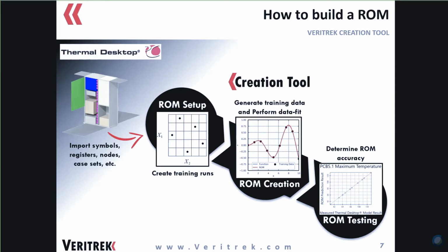So like Derek mentioned before, we start with our high fidelity Thermal Desktop model. And Veritrek interacts with Thermal Desktop using CRTech and Thermal Desktop's OpenTD API. If any of you have heard of that or are familiar with that, that's what Veritrek is leveraging right now. So the first thing Veritrek's going to do is import the necessary model characteristics that we need from our underlying Thermal Desktop model. So symbols, registers, nodes, K-sets, etc.